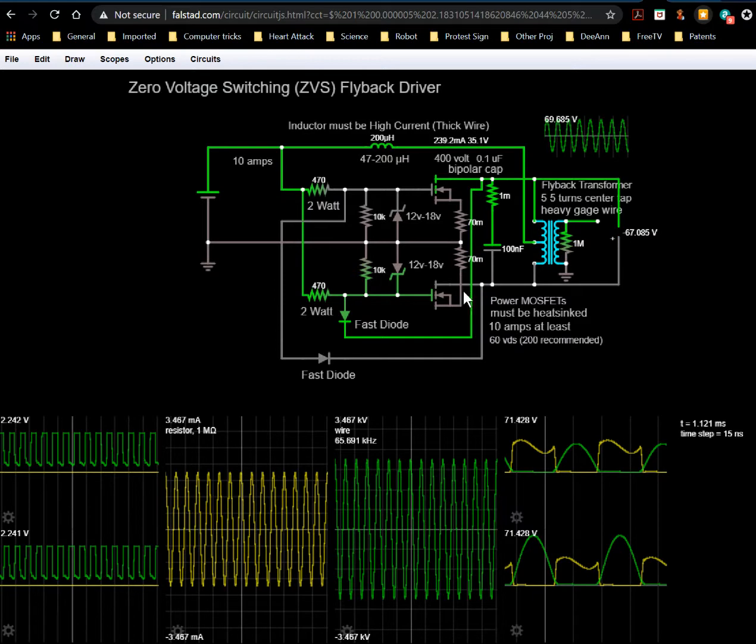But for right now, as far as the transistors are concerned, and more importantly, as far as these diodes are concerned, this voltage, this is at ground now. Remember before ground was over here, but now ground is over here, and relative to ground, since this is at ground, current can flow through this, which does what to the voltage here? Instead of it being the 12 volts it needs to be, it's only 2 volts, so this is off. And since that's off, the resistance is very high through this transistor, and since the resistance is very high through the transistor, that means this capacitor voltage determines what the voltage is here.